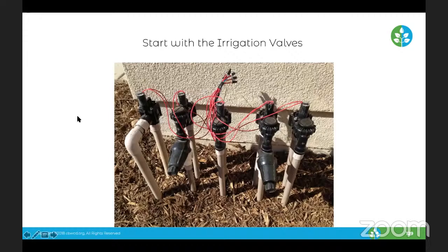So going back to this original picture of the valve manifolds, what changes an irrigation system and how to convert it to a drip irrigation system? It starts with the valves. You can notice that 2 out of the 5 here have something coming off of them. This is a filter, and below it is a pressure regulated system. This is absolutely necessary for drip irrigation because the pressure needs to be lower and constant. So we drop it down to 30 PSI for the entire zone.